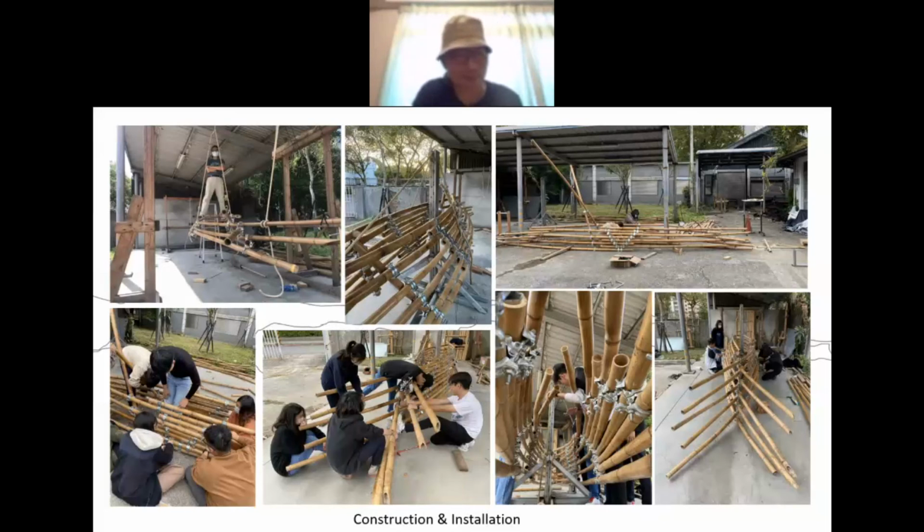Once we have this prototype, the second thing we do is to further force bend and lock the bamboo with the scaffolding clamp. If you look at the picture on the bottom left corner, when the students do that, they forcefully bend the bamboo further in the direction which has already occurred. So they have this pre-stress, and then we use the scaffolding clamp to fix it, so the entire structure is pre-stressed, and that brings about the rigidity that we needed for this structure.